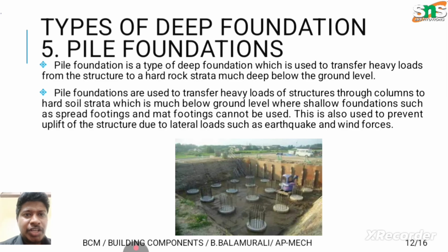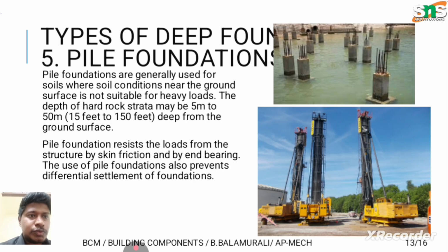Pile foundations are one of the foundations that come under deep foundation. It is a type of deep foundation used to transfer heavy loads from the structures to hard rock much deeper below ground level, more than 3 meters, as already mentioned. You can see the schematic or a real scenario picture of this pile foundation.